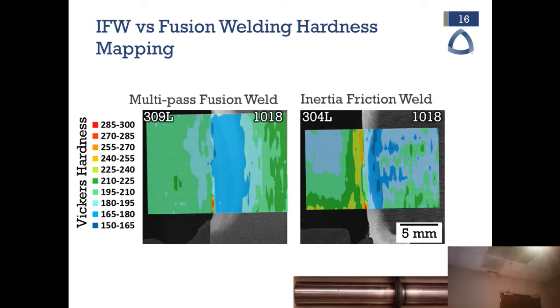So does that make it adhesion? If it was adhesion, I think it would pull apart when you touch them. I want to call it a non-fusion welding process. You see this strain hardened area here, close to the interface? Even though it was high temperature, it still did exhibit some strain hardening there.